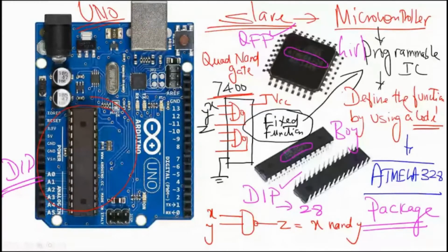Whereas if you take a microcontroller IC, today it does some job, tomorrow the same microcontroller can be used for some other job, and the day after tomorrow it can be used for something else by reprogramming it. It is only a matter of changing the program. So such microcontrollers are very versatile and very convenient for us to design products. That is why we use them. So a programmable device which can alter its functionality by taking a different code is a microcontroller.